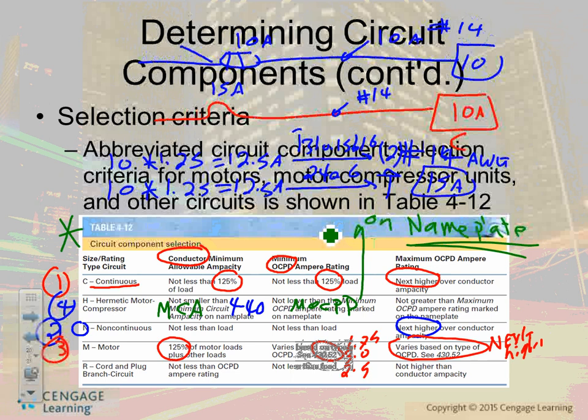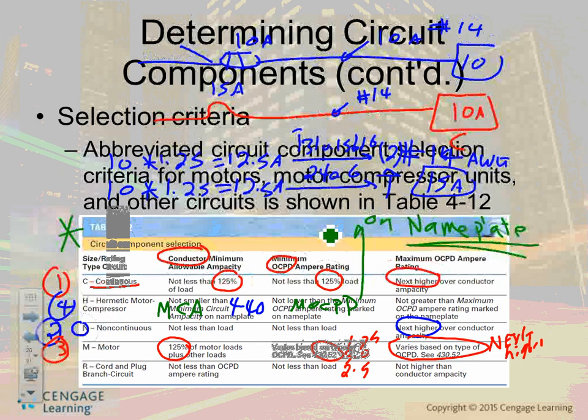So do you have to do any math? No. They will tell you. If you look at the nameplate of your air conditioning, it tells you two things. It tells you it needs 2 conductors, the minimum circuit ampacity, probably 28 amps, and the overcurrent protection device, 30 amps. So that's directly on the nameplate for the AC.